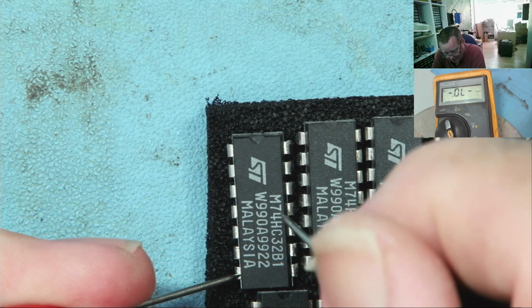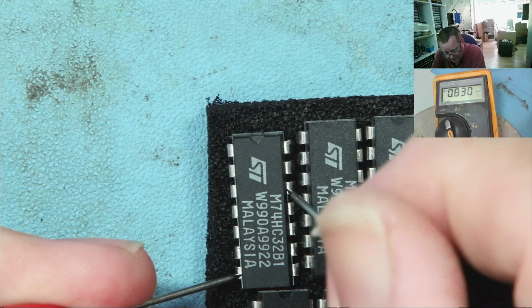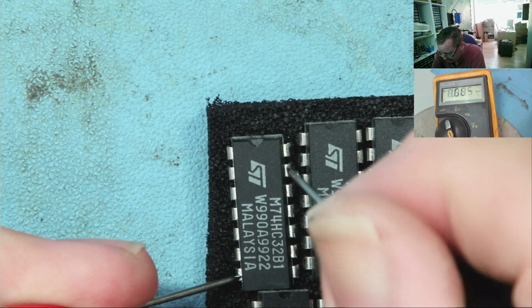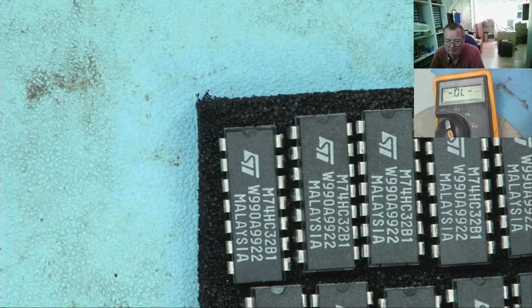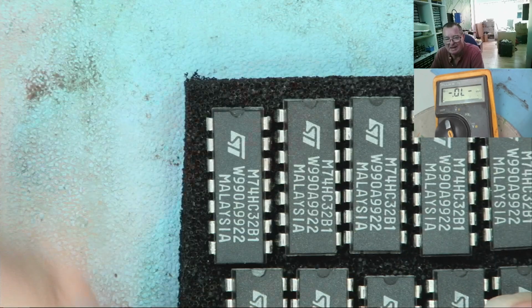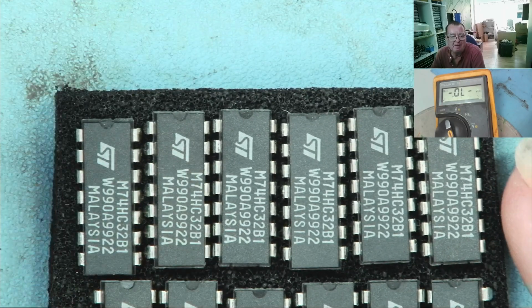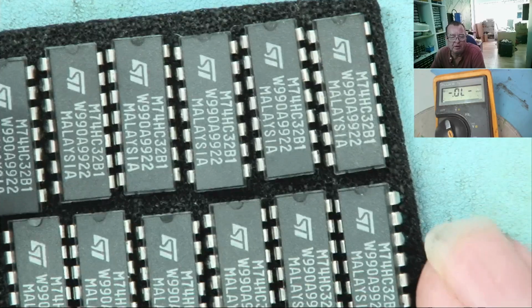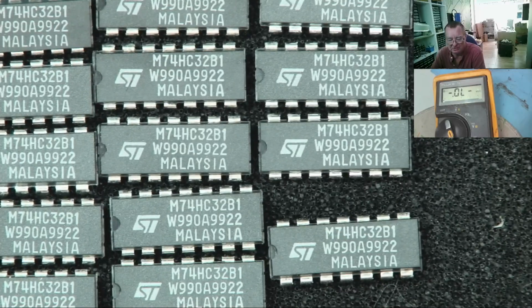Okay, this is the other out, 630, 663, 663. So we can't say what the readings will be for any given chip, but we can say if all the gates in there are the same, or if inputs read the same as each other, if it's just one gate. So that's a way to test logic chips, the same quick and nasty way.